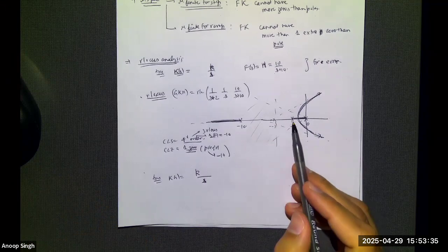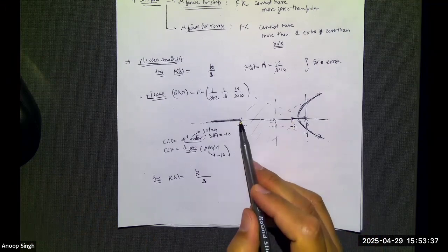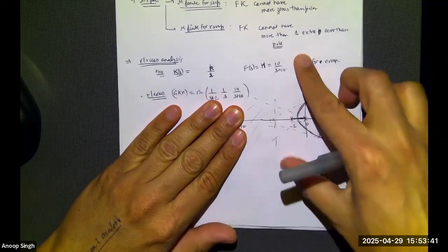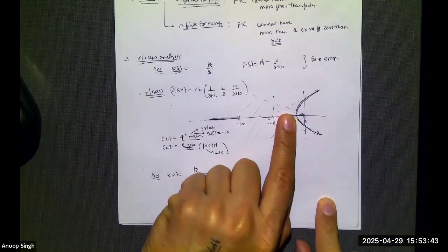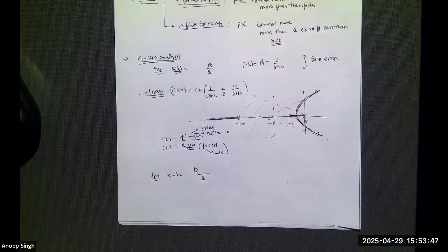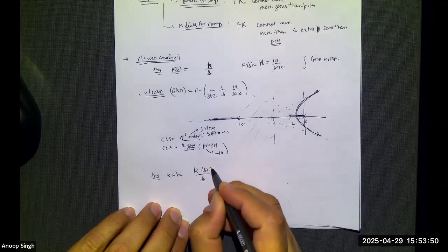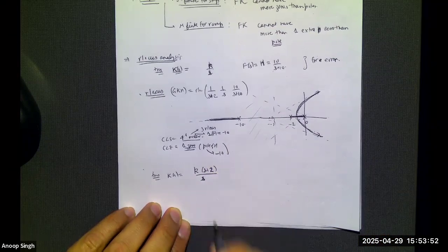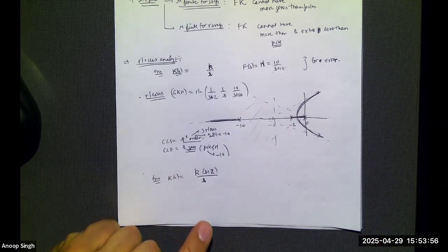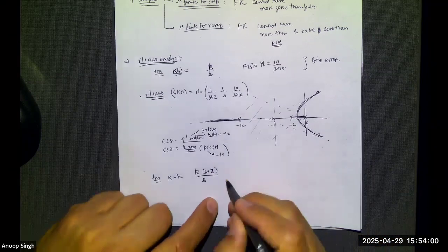Negative. If you put zero over here, that's not gonna help. That's just gonna go like this. Root locus will go like this. If you put zero over here, then the root locus is gonna come together and go like this. Okay, so I'm gonna try a controller of this type. So you put a 0 at 2. This controller is called a PI controller, proportional integral controller. Okay, so let's try this controller.